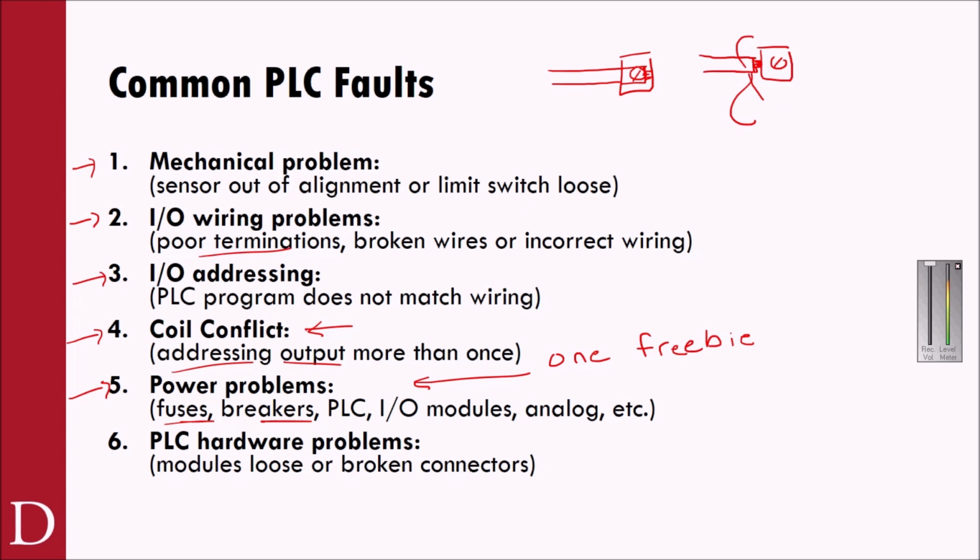The reason why I say get one freebie is because you can get a voltage spike across the line. You can get a little bit of a spike or a surge or something like that, and you can't always control those. Those are somewhat intermittent. However, if the breaker trips and you walk up to the machine and you turn it right back on and it trips again, this would be true in your house. This would be true in an industrial environment. You ought to troubleshoot at that point, on that second trip, especially when you turned it on and it tripped right away. I wouldn't just keep trying to reset it. Oh God, it turned on this time, because again, the breaker's telling you something. It's telling you there's something wrong. So that's an important detail for you.